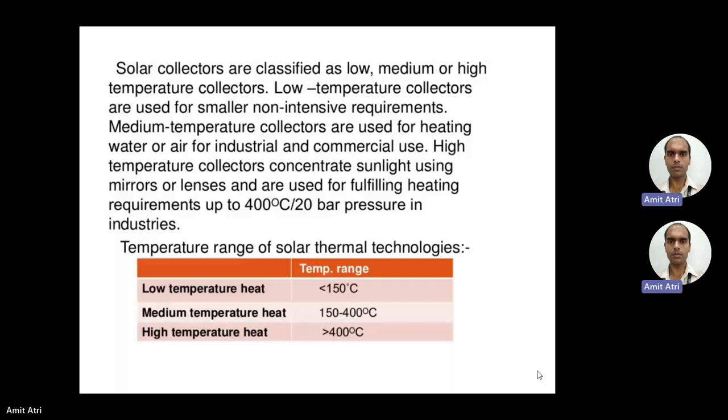We will discuss this one by one, then go into detail. The whole solar panel absorbs light, because the collector and the absorber are the same, so the area is more. Non-concentrating solar collectors are generally used for low and medium temperature. In contrast, concentrating collectors have a larger interceptor than absorber, meaning the absorber area is less.